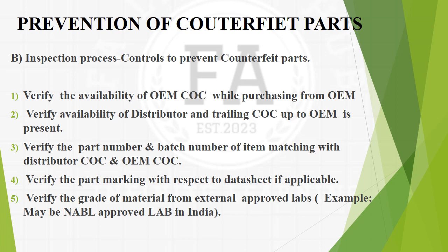So if you are purchasing from a distributor, ensure that we are getting distributor COC and OEM COC. If it goes through different distributors before reaching us, ensure that we are getting all trailing COCs from all the distributors, up to the OEM COC. So this is what the incoming inspector needs to ensure.